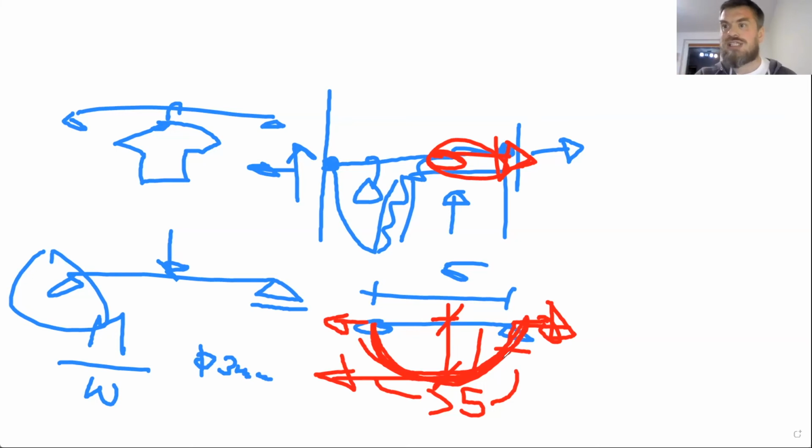The structure itself, as deforming, can generate additional stresses. It can strengthen itself. It can weaken itself. It can run away from loads. And those kind of things are nonlinear geometry. So every stability failure would be a nonlinear geometry problem, and a tensile stress you can see here is a nonlinear geometry.